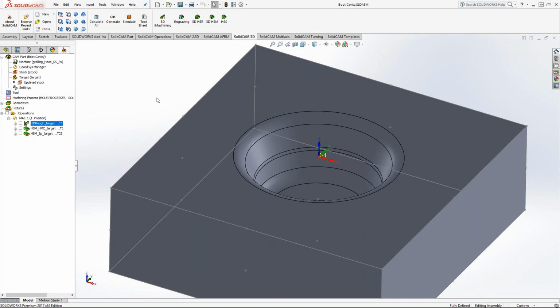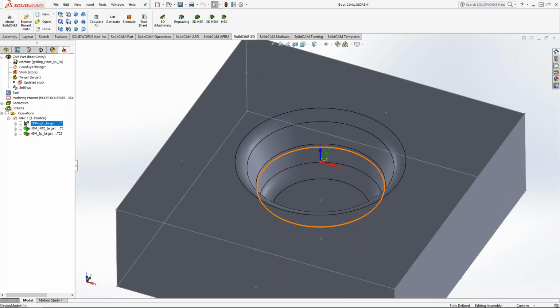And that was mostly with a bull nose that you were running? That was bull nose and ball nose. Most of the time, if I was doing more vertical wall work like this cavity, which is mostly vertical, I would use a bull nose because I could get a more constant surface footage on the cut around the periphery of the tool.